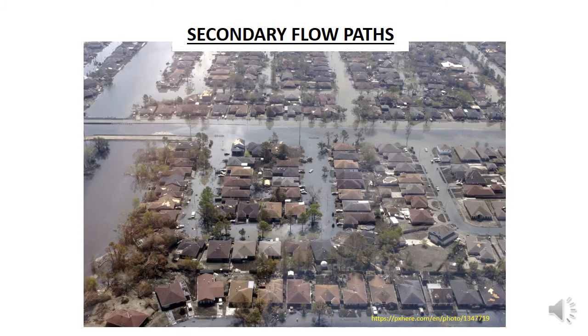Having said that, sometimes we need to shape the land so the roads do flood. Stormwater is the surface water resulting from rainfall. A stormwater system is a series of manholes and pipes that collects the stormwater and conveys it to disposal into natural water systems. This is called the primary stormwater system and it can handle most rainfall events.